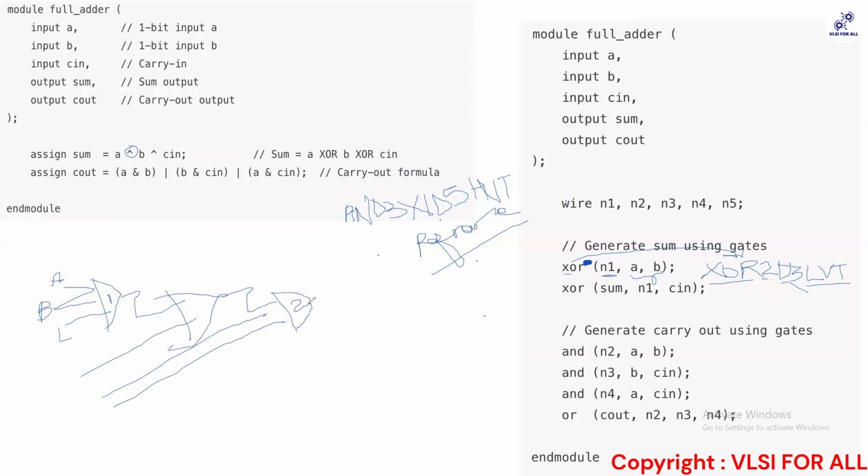Now when you read your netlist, both of them are the same, but how will you filter out which is cell 1 and which is cell 2? So I have to mention a cell A and, let me say, A1, then I will have my ref name, and then there is something what it is doing. Now when you read in your design, you will have all the instance names. Ref name has to do only with your library. When you do a report, when you ask for the ref name of this design cell, the tool will tell you, okay, I am this kind of a cell.